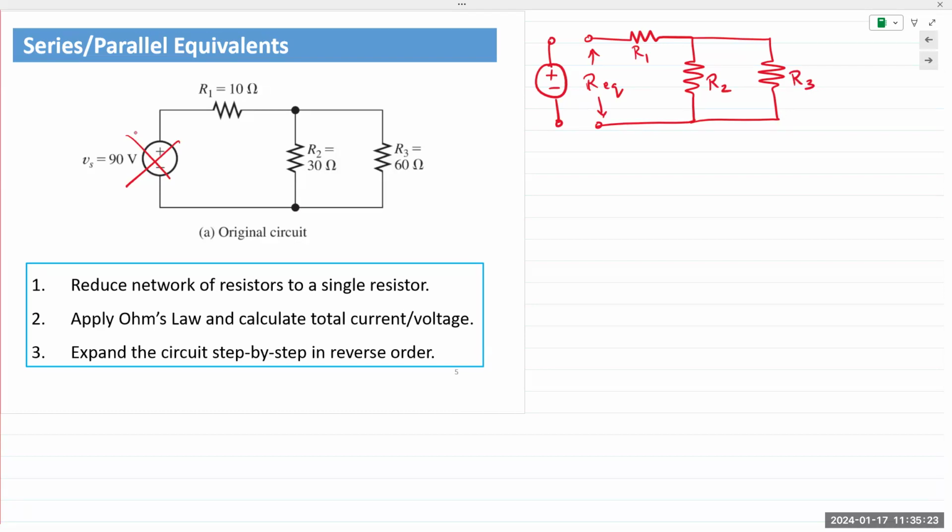Now here's where I talk about passive reference configuration, as well as the points about assuming the voltage polarities and the current directions. Okay, remember I said it'll make more sense when we come to an example. Well, this is that example. So this is the beginning of the analysis of our problem. We have no idea of the voltage polarities and the current directions that appear in the circuit. We do know that once we apply a voltage source, current will flow in the circuit, currents will flow through each of those resistors, and a voltage will appear across each one of those resistances, right?